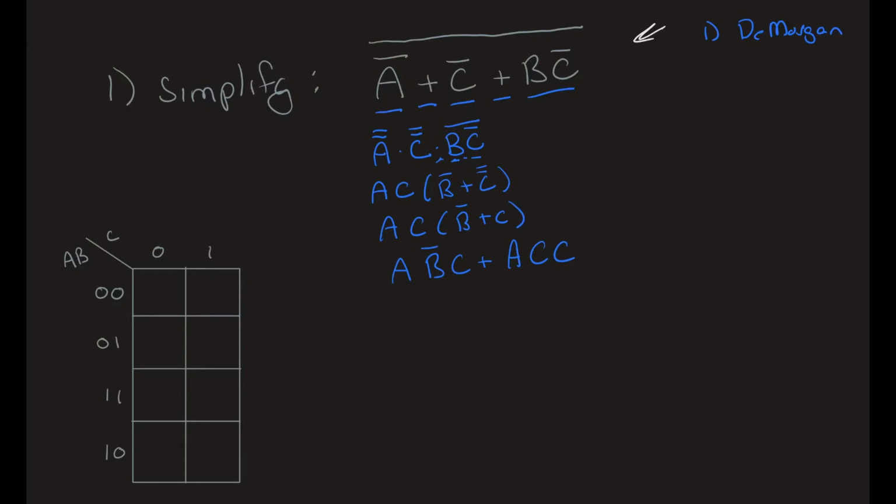Okay, so what do we got to do? Well, remember, we don't need two C's. And move this over, I should erase that one. So, are we done? No, not yet. Not in standard form. Turns out we're missing a B there. And so, this will be true at 1, 0, 1. At 1 and 1 for A and C, but B could be 0 or 1.